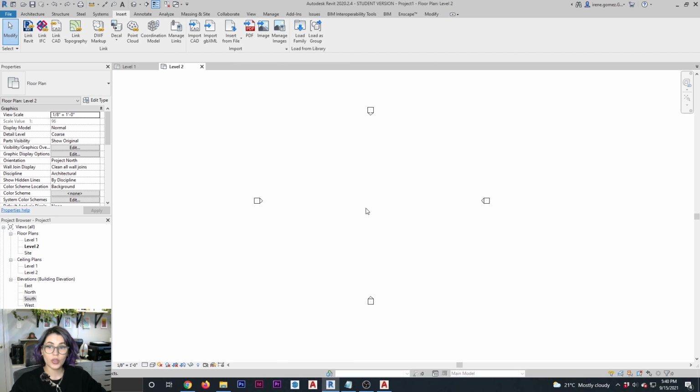Another thing that you can do is bring your reference drawings on elevated views. By default, we always think about floor plans, but sometimes the reference information that you're going to be given will include elevations. This is particularly common when you're working with buildings that have unusual roofs that you have to replicate. So in those cases, all you have to do is come to your elevations in the project browser.